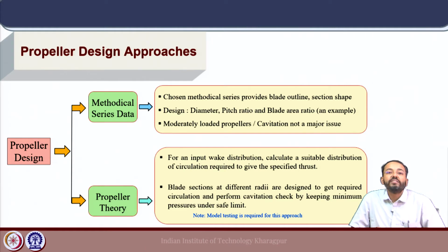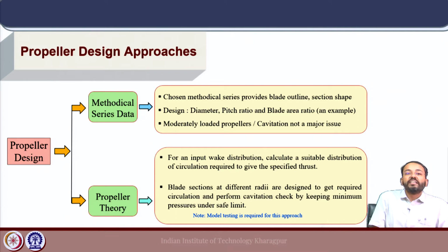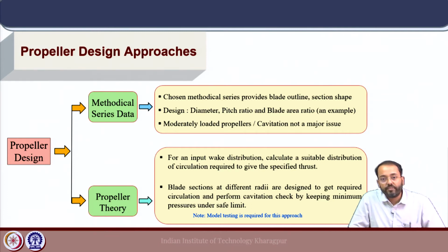Why? Because cavitation checks need to be performed in a detailed way for different blade sections, so that the cavitation occurrence is avoided in the design process itself.